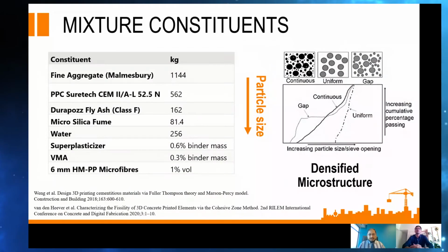Yes. So one of the critical aspects that we consider in 3D concrete printing is, can this material physically retain its own shape? As you're depositing the material and building vertically, each layer is stacked upon the previous layer, so the structure needs to be able to carry the aggregated weight of all the layers that have been deposited. And if you start getting free form shapes, you're creating eccentricity.